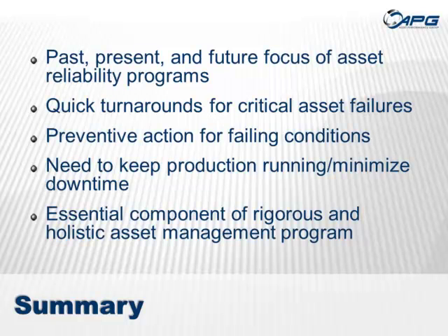Also, an effective and focused RCFA process helps to find and fix asset deviations, when and where they occur, so that we can quickly turn around, as you mentioned in the last question. These new failure modes that we identify from an RCFA can be used to prevent future problems. They can also be used to investigate failing equipment, not just failed equipment, but any sort of irregular asset conditions, so that we can prevent further damage. Of course, all of this is designed to maximize production and equipment uptime. And so RCFA, in summary, is an essential element of a holistic and comprehensive asset management program.